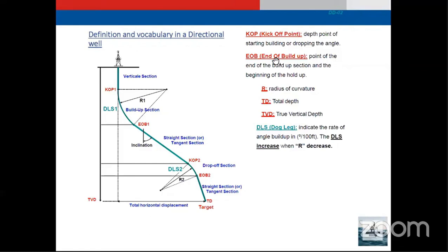After each stand, the system sends mud pulses to measure the inclination angle, the azimuth angle, the measured depth and true vertical depth. This data is collected by the surveying tools, and we use it to keep the well on plan. So we plan first, then we monitor each execution of drilling with surveying and know all parameters.